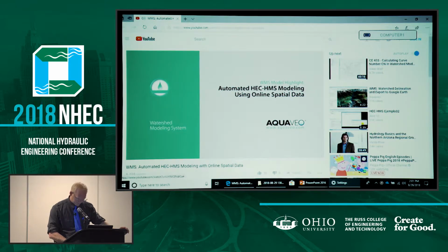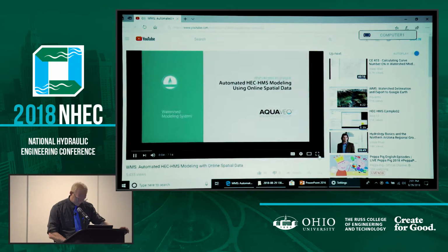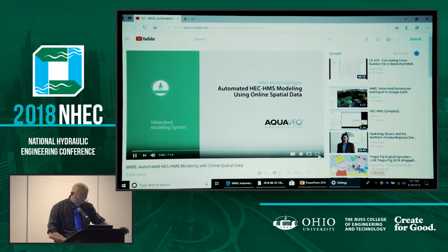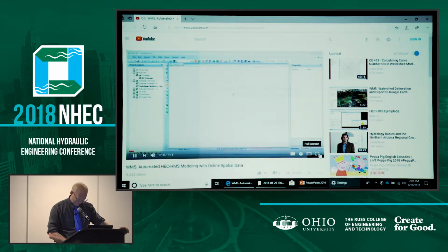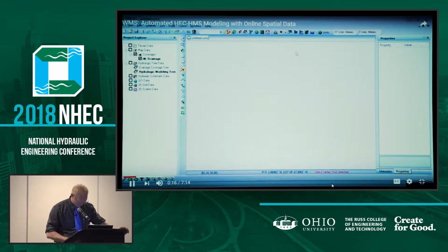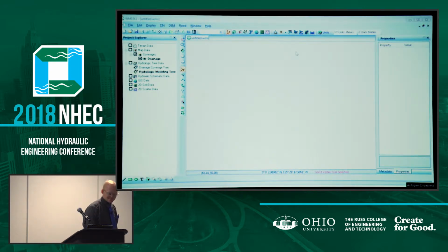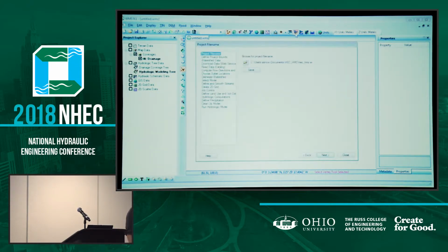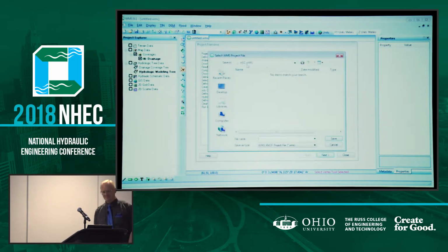This video shows how simple it is to use WMS to gather data and create an HMS model of a watershed near Park City, Utah. We will use the WMS Hydrologic Modeling Wizard to download data and to automatically build an HMS model. After the model is built using WMS, we will export it to an HMS file and run the model in the HMS interface. The first step in defining an HMS model is to define your project file name.